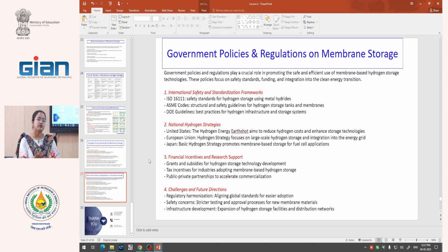So one of the technologies we can use is evaporation of solvent. After casting, we keep it under vacuum or at an inert temperature. That is one possible solution. Another possible solution is sintering of the membranes, sintering of inorganic materials, which will give you a more dense structure. Or you can have coating of your membrane onto a surface. I was showing once a palladium coating method being used in a rolling machine.